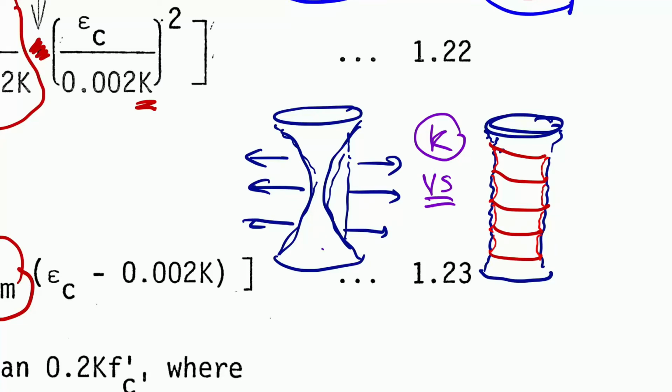So if you break by this, then you get the f'c. But if you have this, then this is K, which is the part that maintains. So after this point, you have the degradation of the concrete inside this confined core, and then it will be the ductile mode of failure, because the steel hoop starts acting together with your concrete.